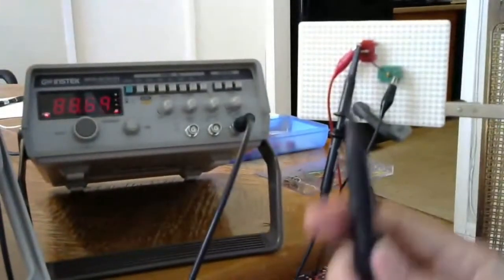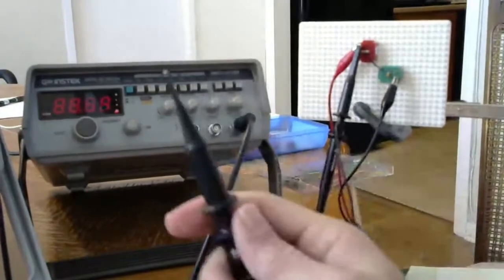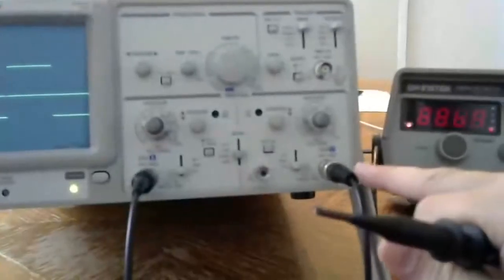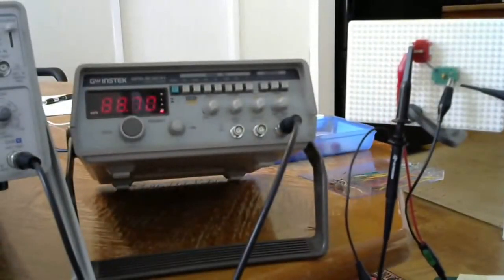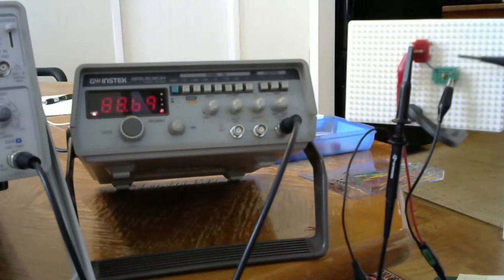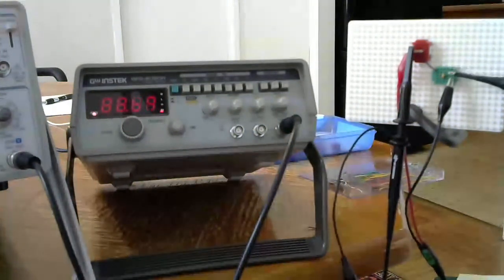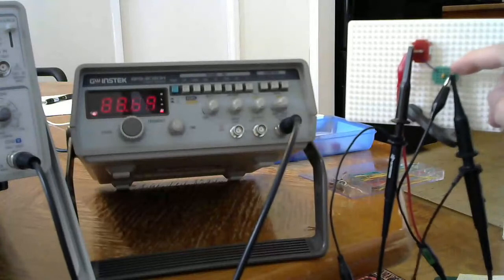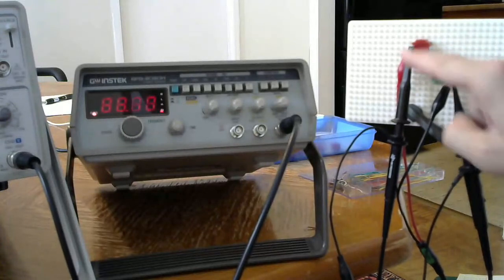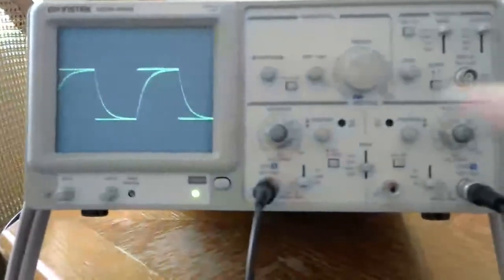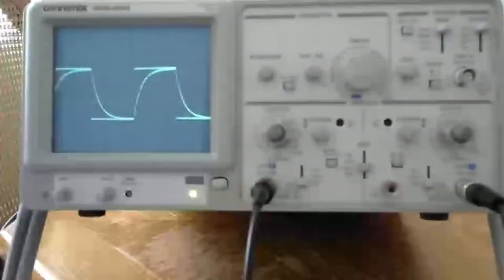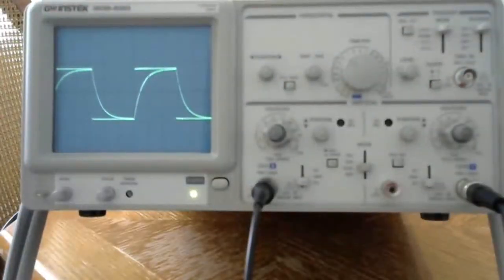Here's my second probe, which is connected to channel 2, and I'm using it to look across this capacitor. Here's the ground, the bottom of the capacitor. Here's the top of the capacitor. If I connect it here, I'm looking at the voltage between the top and bottom of the capacitor, same ground as the battery. And if I put that on there, notice I now see my capacitor voltage at the same time as my input battery voltage with the switch.